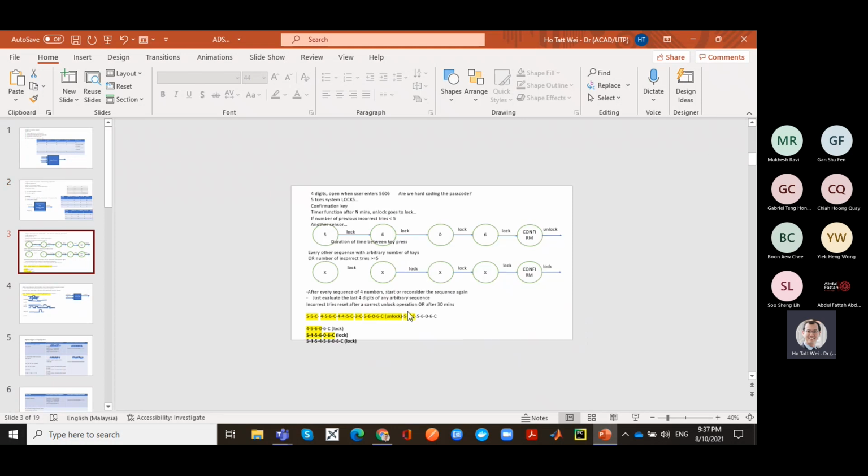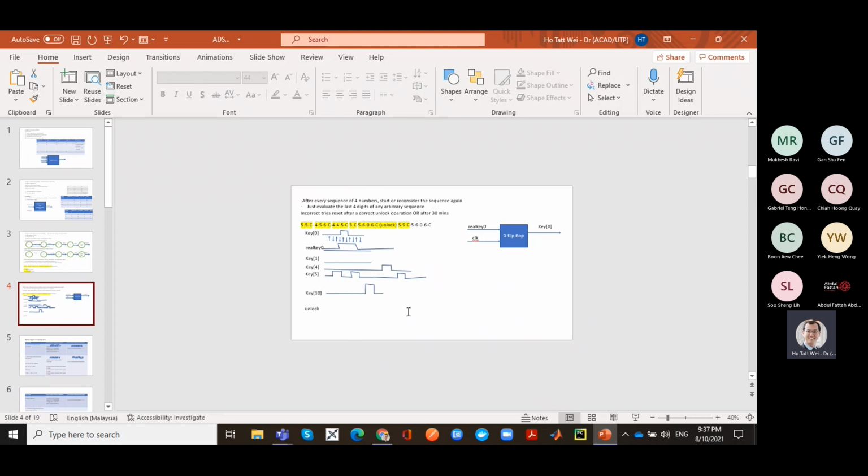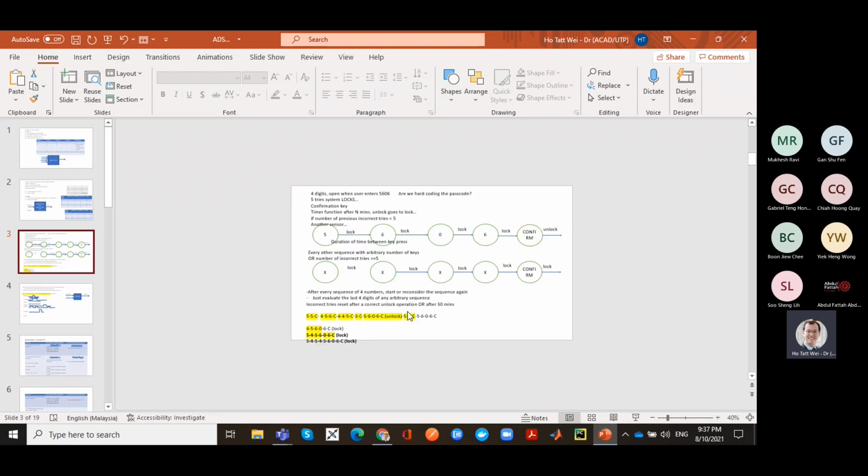And then you will define the sequence of inputs that you anticipate to receive, and the response of the circuit, which is also a sequence of output ones and zeros in response to a particular input pattern. And you have to do this as exhaustively and comprehensively as possible. You have to somehow find a way to document and explain this, okay? Normally you start by explaining what happens in the case that you want it to happen, like expected inputs. So these are the expected outputs.